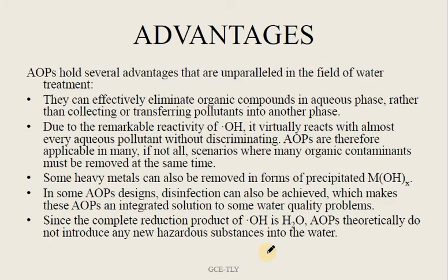AOPs are therefore applicable in many, if not all, scenarios where many organic contaminants must be removed at the same time. So we will adopt AOP in such conditions. Some heavy metals can also be removed in this AOP process. In some AOP designs, disinfection is also achieved in the same process. Since the complete reduction product of OH is H2O, AOPs do not introduce any new hazardous substance into the water, which is an advantage.